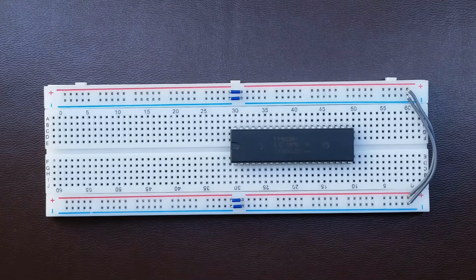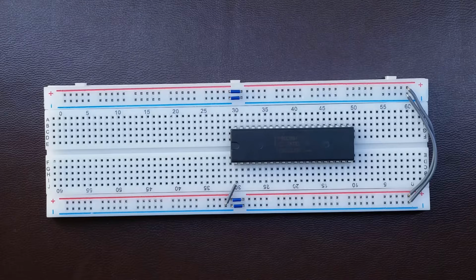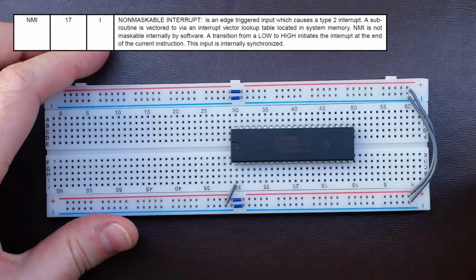Let's start with pin 1. It is ground, so let's put it right here. Then pins 2 to 16 are the address and data lines. We'll use some LEDs later to be able to see their states. Then we have pin 17, NMI. That's an input. NMI stands for non-maskable interrupt. We're not going to use interrupts yet, so we need to keep it low.